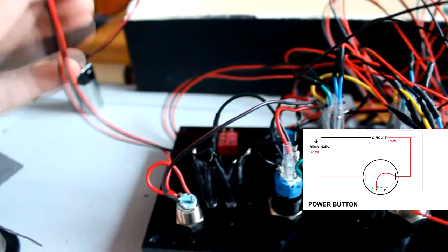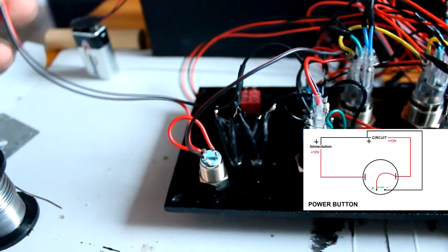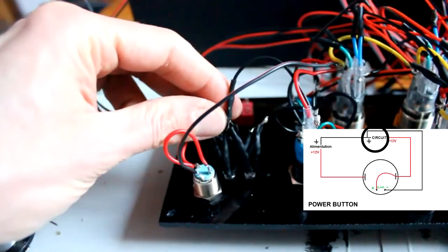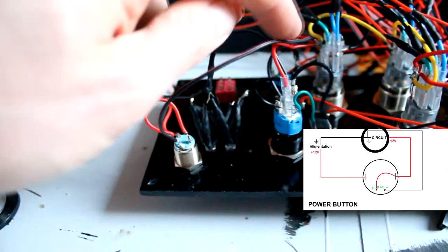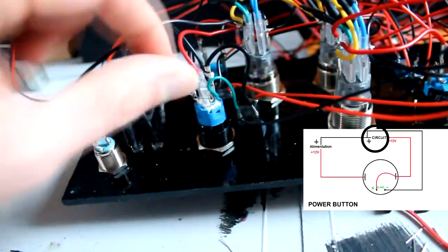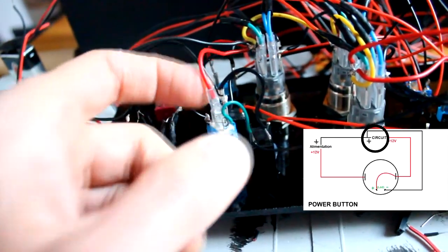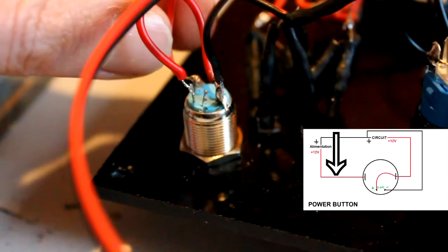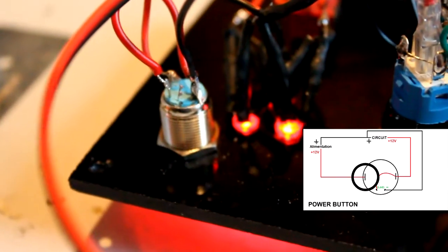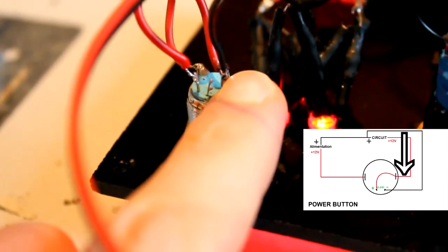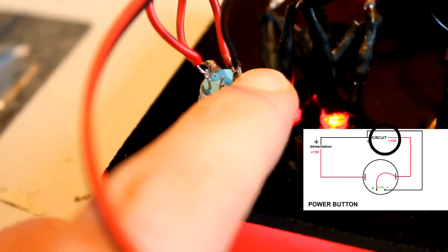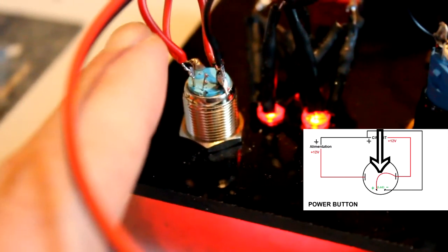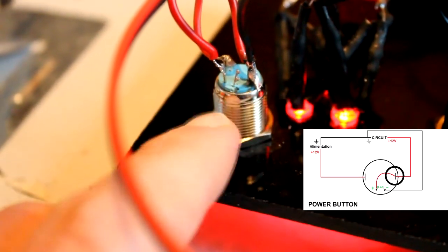On the power button I soldered the wires that will power the whole circuit. I soldered the black ground wire to the three cathodes of the three LEDs of the landing gear. Then it goes to the first ground on the parking brake button, and it goes to the other ground on the other components. The red wire of the power supply is soldered to the left leg of the power button. The wire on the right leg of the power button comes from a plus 12 volts taken from the circuit, and here I have a loop between this leg and the plus pin of the integrated LED.